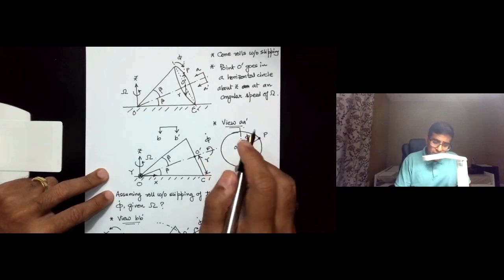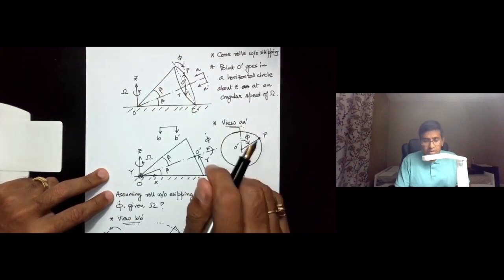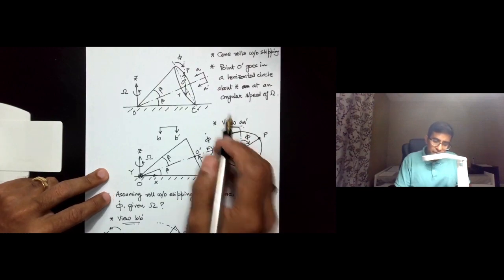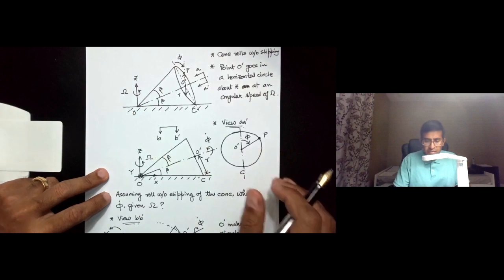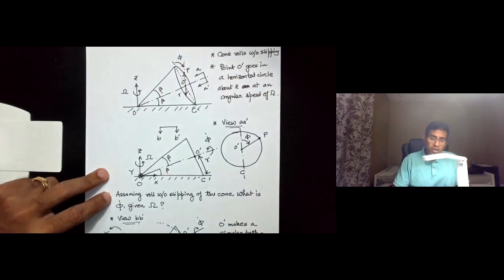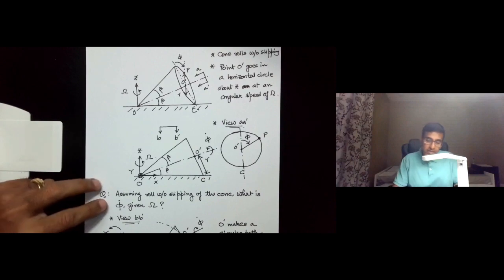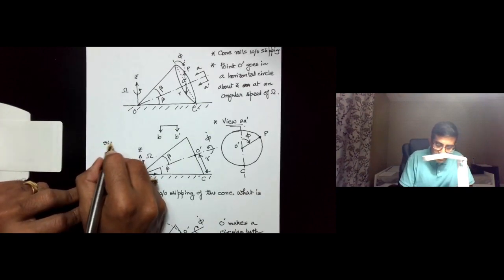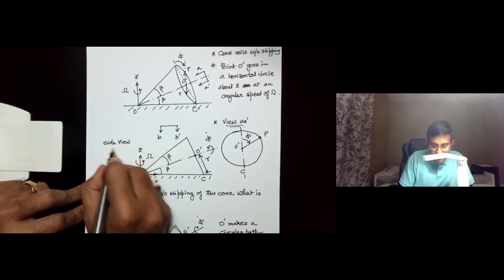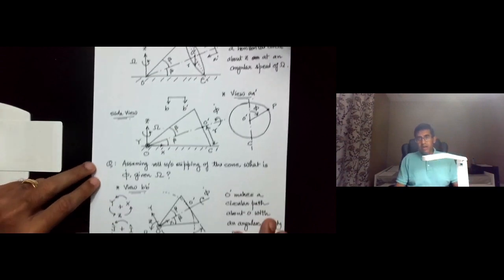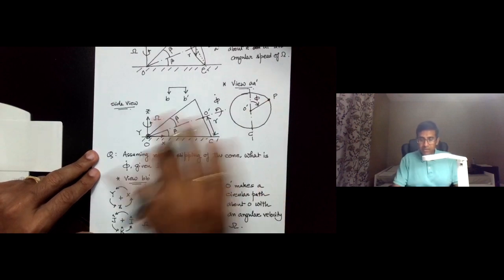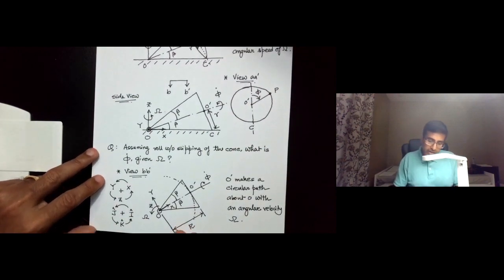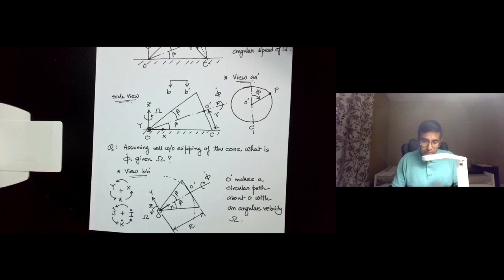And this diagram is a perspective view, so I'm not showing the x and y over here. You can assume that this is an approximate view because I'm showing the face of this base circle, which strictly in side view is not going to be visible. So let me call this the side view. So these three diagrams are actually forming the engineering diagrams for this cone.